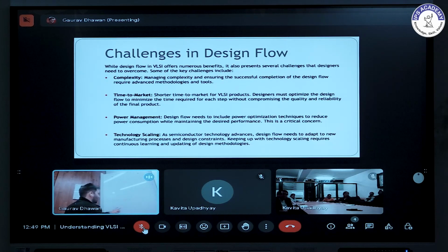There's a P substrate, a P well, a source, this is drain, N plus, and here comes the channel, right? This is your silicon dioxide, this is your gate. This channel length is what we call the transistor size, whether it's 28 nanometer technology or 16 nanometer technology. So the distance between source and drain.